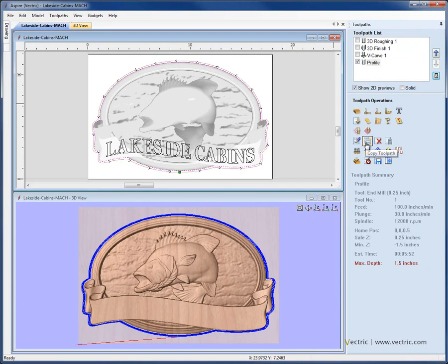The next icon allows you to make a copy of your selected toolpath, and the icon following that will allow you to delete any selected toolpath in the list. The final icon on that row would let you force a recalculation of all toolpaths. For instance, you may change the material size, in which case you may need to recalculate all the toolpaths to take that into account.